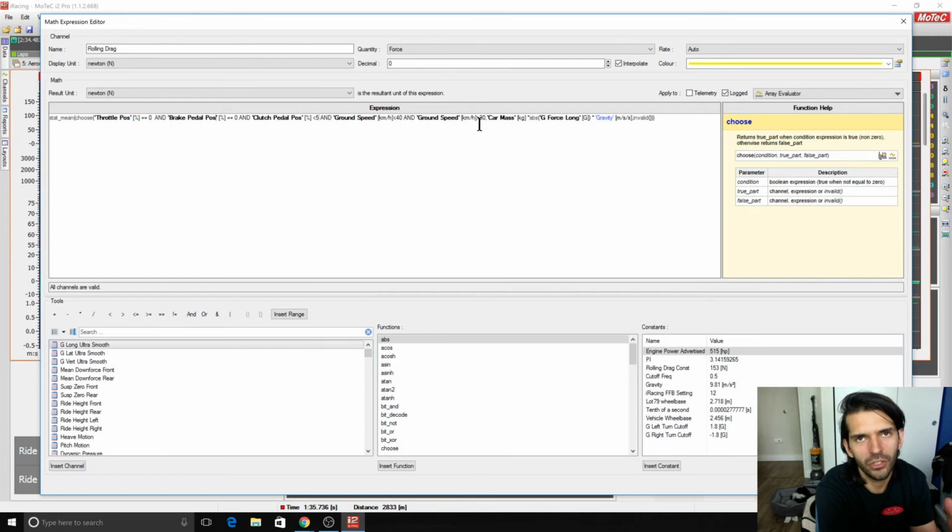We can safely assume that at 40 kilometers per hour, there's no aerodynamic loading that's worth anything. We can count it as negligible, so then we can just perform the calculation at that speed. So then you have 10 kilometers per hour that it averages, and then it calculates, which is just a basic equation of mass times acceleration, which is equal to force.